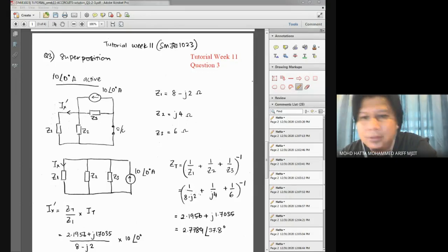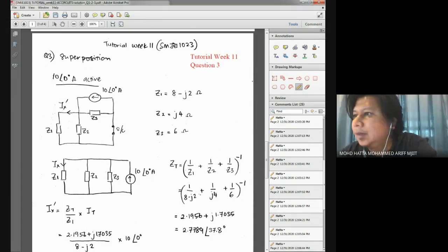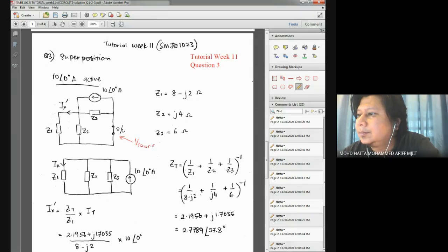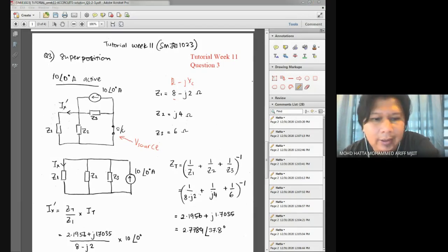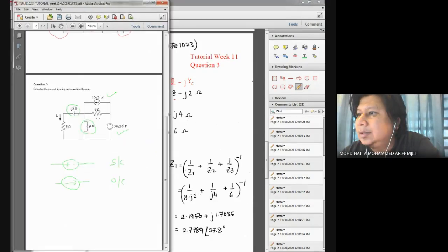Now I try to change back into maybe red this time. And if you look at the voltage source over here, I treat it as a short circuit, V source. And the first thing I did was I defined what my elements are first at each branch. The first one we have Z3, where Z3 is the combination of resistor R, and also minus jXC, our capacitor.